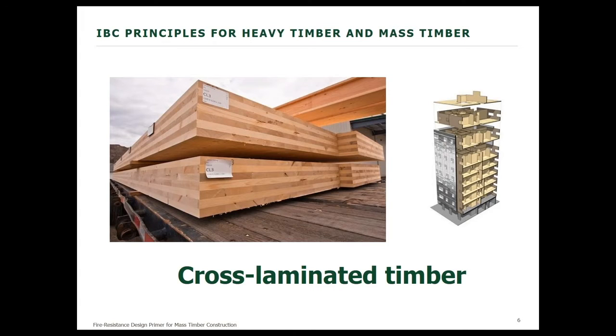Well, here we are, cross-laminated timber. Mass timber as a separate building system was really born because of one new product, cross-laminated timber, or CLT. CLT represents essentially a sea change in wood construction because of the new structural and fire resistance characteristics it represents for wood construction. Never before had we contemplated solid wood floor and wall sections of this size, or this mass, used in a similar manner to that of concrete walls and floors.